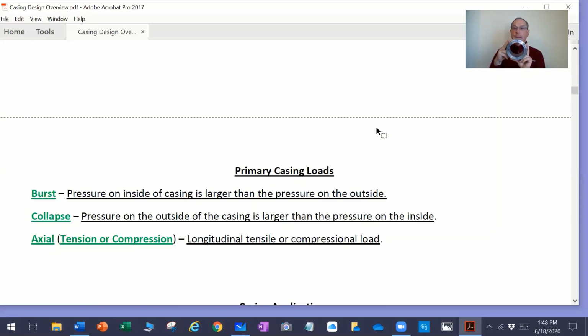And it's amazing that this is made out of 135,000 yield strength material that has a burst rating of around 37,000 pounds. So when you think of something that's 5 inches OD with 11/16 wall thickness and it's rated to 37,000 PSI, it kind of gives me the impression it's like a cannon that we might shoot rocket shells out of. It's pretty intense equipment that we use in casing sometimes.